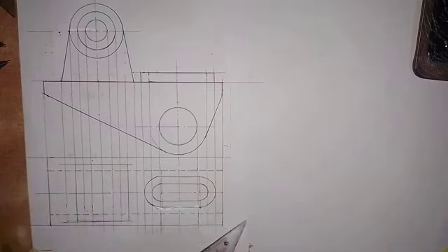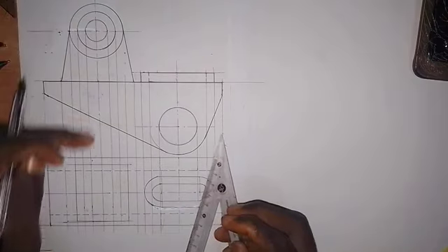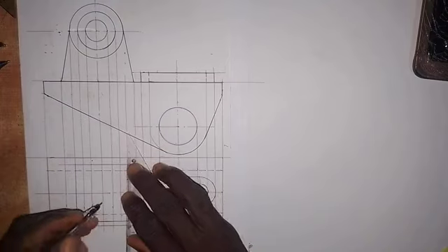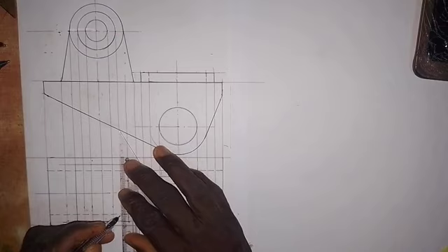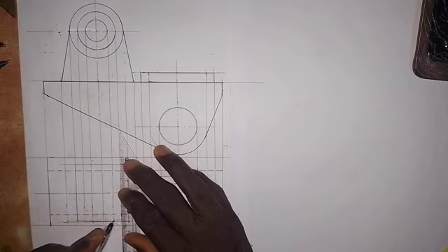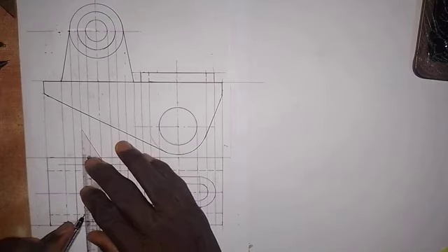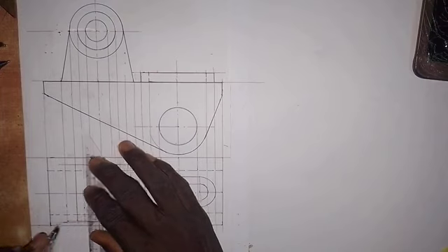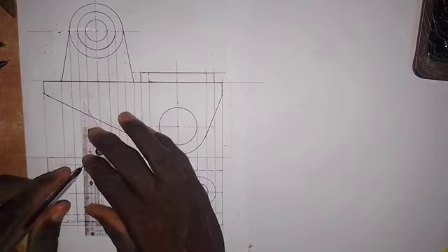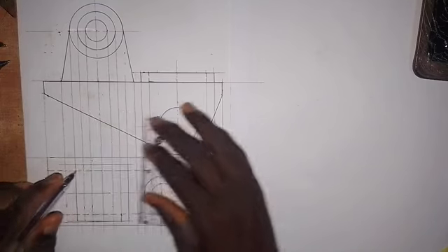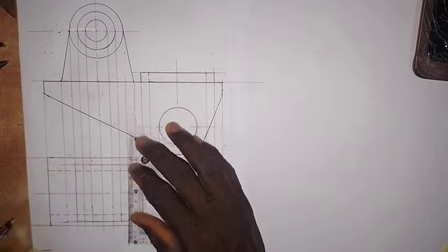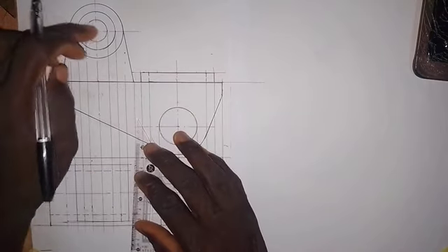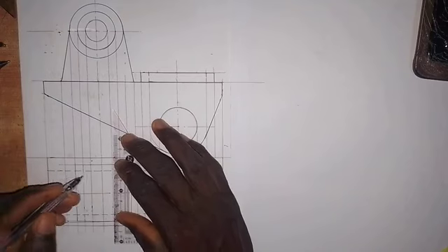So the other thing that we have here: this one will be hidden. A part of it we just have at the front here, to be drawn with short dashes line. I'll also draw this with short dashes line. We have the same thing here, so we draw with short dashes line. We also have it here drawn with short dashes line. That is its edge, while this inner one will be hidden completely.